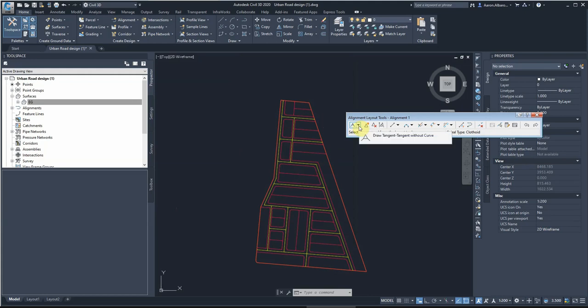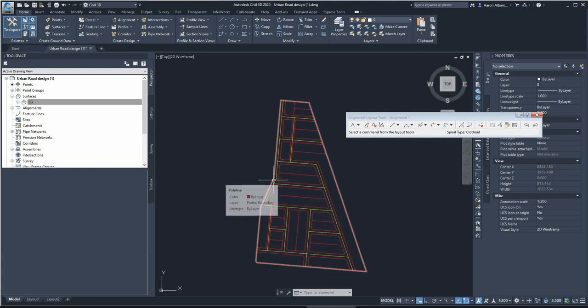This is one of the main first differences that we will see now. Usually for an alignment on a rural road design, we used to care a lot about the speed limit on that road and then calculating our radiuses, if you remember, from the equation that we had from the Austroads Part 3. In this case, as we discussed before, in urban roads or suburban areas, put it this way in a clear way, we don't worry too much about the radiuses. Number 1, because initially, if you look at the shape of the development here, we're trying to minimize long stretches of roads, as well as we're not creating a comfortable track for cars to speed up.